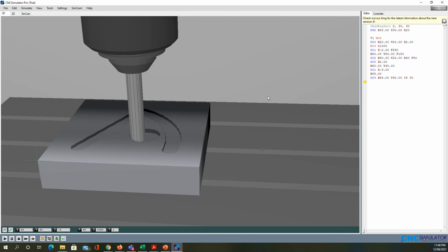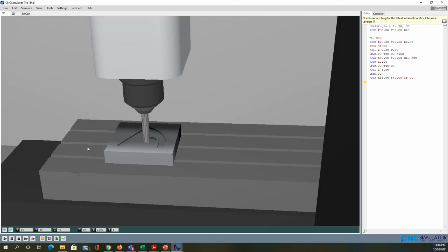Now you can copy any code you make and put it here, and you can make any shape on your own work part, and within a short time you are going to be professional with the work. Actually, the part we made with assignment number one, you can bring the same code here with your own work part, define the center location. You can even put it in the center if you would like to have the 0 point in the middle, and then show us how you do the machining operation by using this simulator tool.